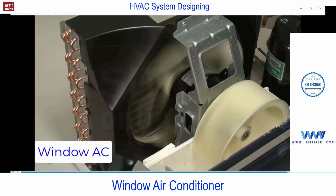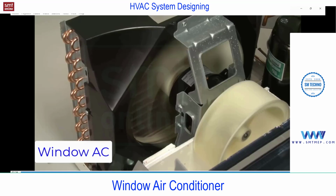A slinger ring on the condenser fan blade picks up this water and sprays it onto the condenser coils to help the coils dissipate the heat. And this spraying of water on the condenser coil, you'll not find in all the models. In some models you'll find. This will help to increase the efficiency. The same condensed water is going to be available in the drain tray at the bottom, so it can be utilized to cool the condenser to increase the efficiency, but not in all the models.